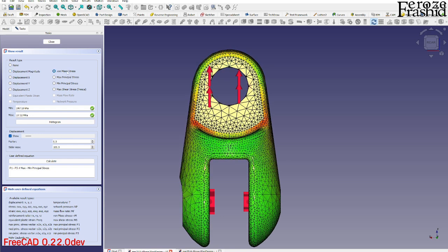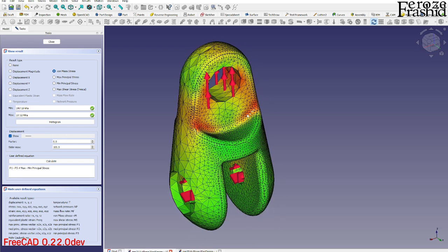And we also can take a look at the stress. It says that 27 MPa is developed stress, and maximum stress is being developed at somewhere here and in here. So remember, when we were looking at the property of this material, the yield stress was 300 MPa.